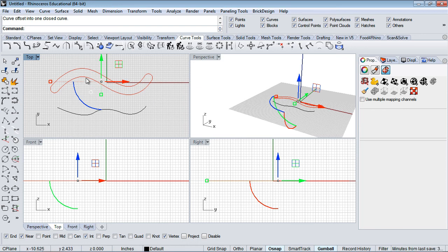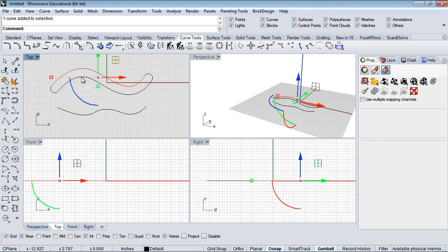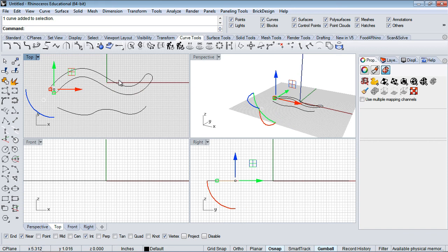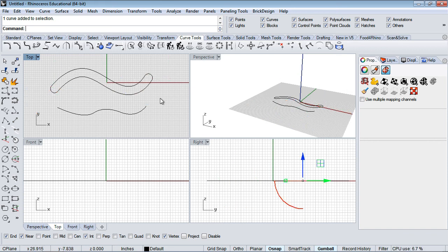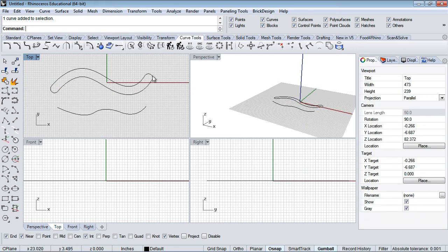And there's other things that we can do too. So let's say we have this curve, but we want to select some individual elements. We can explode the curve. You can explode any geometry into its component parts, whether it's a surface, a solid, or curves. So if we do that, you can see that it exploded the curve into 4 segments. So now we can go and pick out those individual elements again. Okay? And we can edit those. So if I wanted to delete that, then I can just delete that.